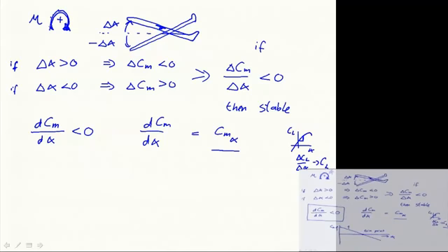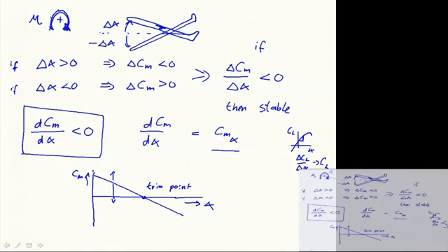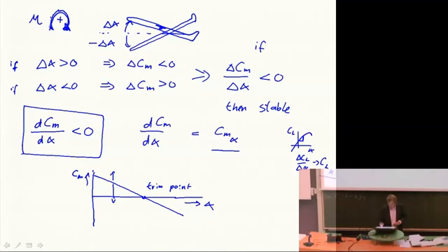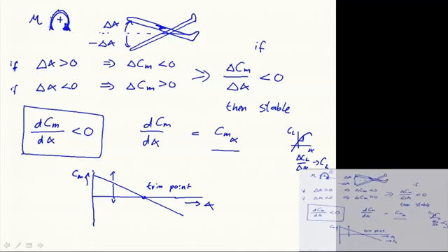Well, we can move this curve up and down by changing the trim angle, or basically the change of angle of attack, between the horizontal surface and the wing surface. So, but to have a stable equilibrium, we first need an equilibrium, so there needs to be a trim point, and we need a line going down. You could also say that when the lift is 0, I mean this goes up with the lift, right? The CL will also go up in that direction. Our lift is probably larger than 0. So if we make sure that when our lift is 0 and the Cm is then positive, then we will certainly have a trim point. So a very simple relation that we also say often for stability are 2 criteria. There needs to be a trim point.